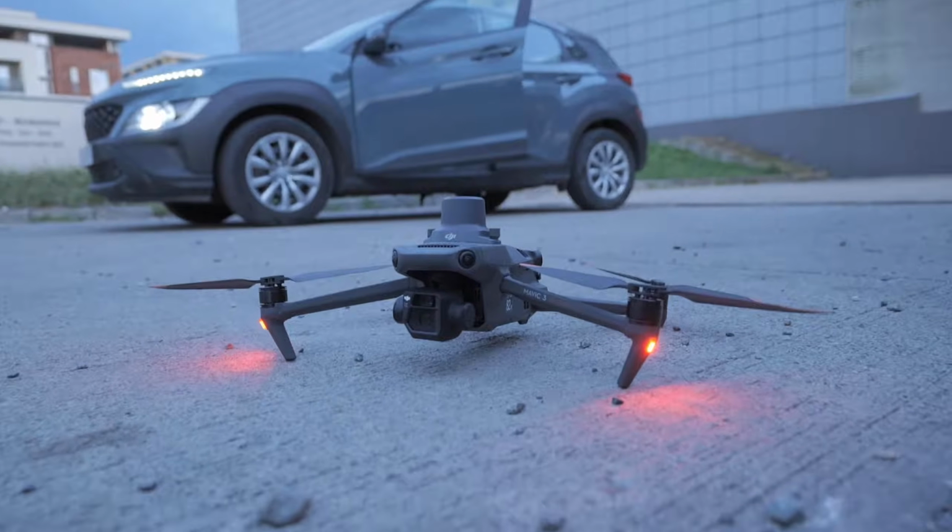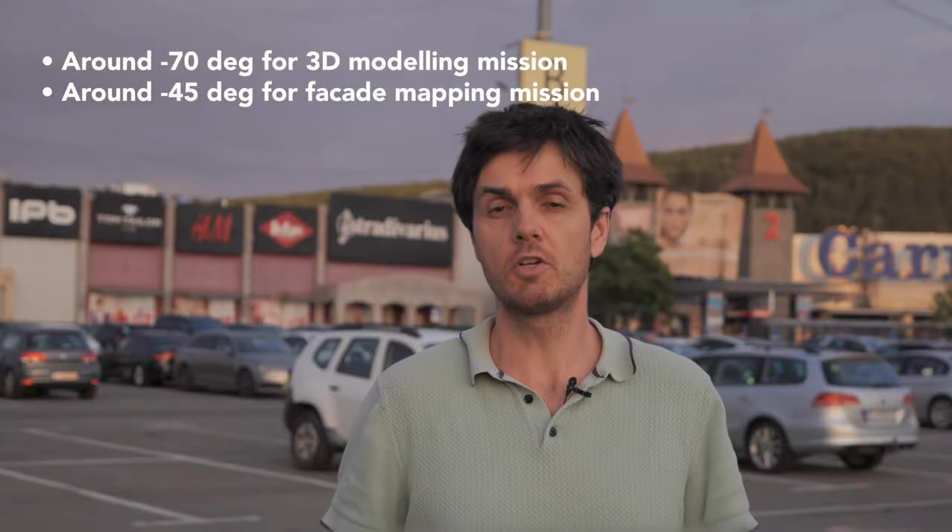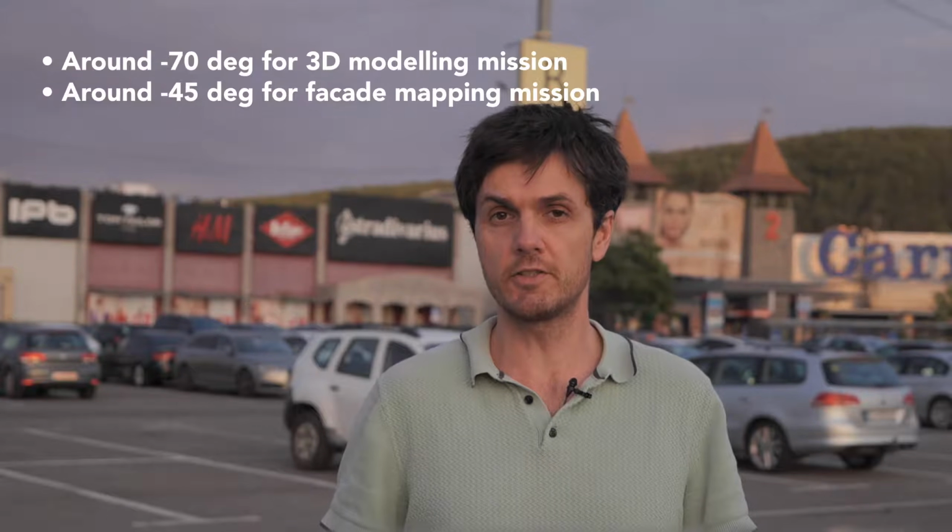Hello, today we will be capturing a large shopping mall using the Mavic 3 Enterprise to create a 3D model of the site. Because it's such a large site, the Mavic 3 Enterprise is well suited for the task because of its battery life and speed. We will also be capturing the facade of the building in a separate mission, having a gimbal tilt of around 70 degrees to ensure we capture the vertical structures on site. Let's take a look.